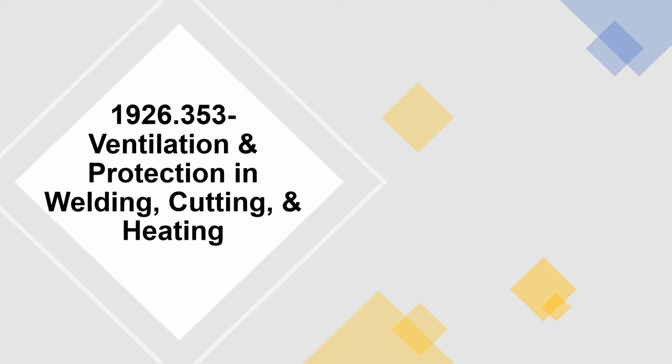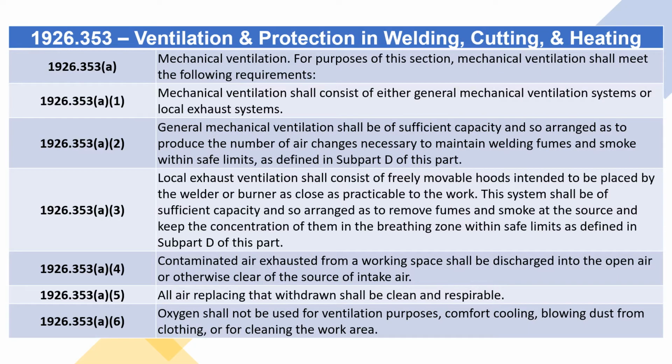1926.353 Ventilation and protection in welding, cutting, and heating. A. Mechanical ventilation. For purposes of this section, mechanical ventilation shall meet the following requirements. A.1. Mechanical ventilation shall consist of either general mechanical ventilation systems or local exhaust systems.